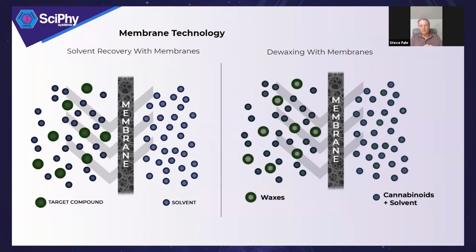This is really another very interesting cost-reducing opportunity. In certain cases, especially when you're doing lower volumes, and instead of going continuous you want to stay in a batch mode, at least on a short-term basis, it's feasible to use the same type of membrane equipment, or even the same membrane unit with multiple housings on board, to do both the solvent recovery step as well as the dewaxing step.